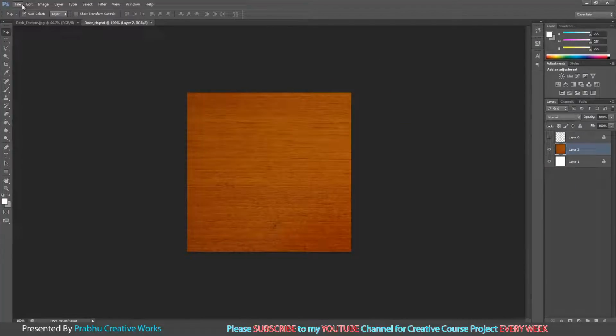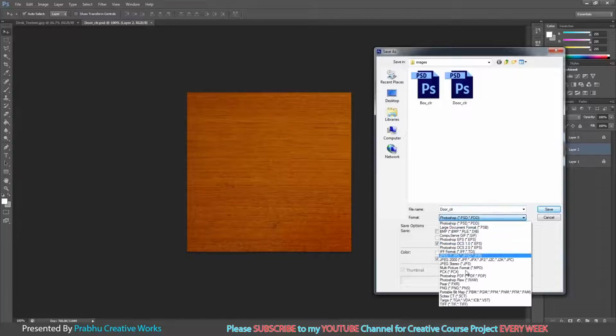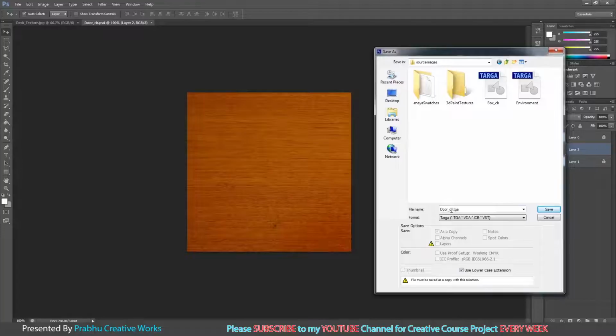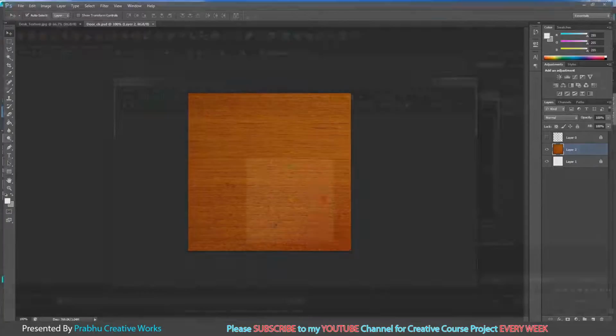Now I want to save this as a Targa file in source images. Go to File and choose Save As, and save as Targa. Go to your source images and choose door_color.tga, choose Save and click OK. So now I go to Maya.